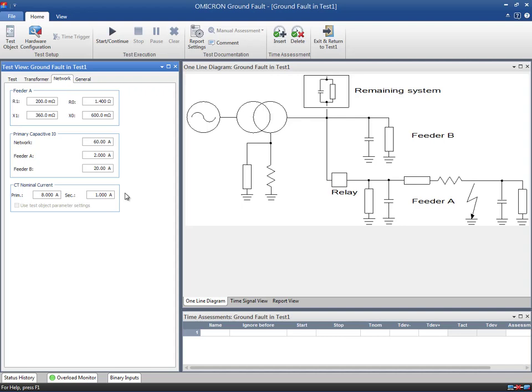If you get the message that the ground fault currents are too high, just increase the number of turns through the cable type CT. For secondary current injection, enter the CT ratio as specified in the datasheet. Select the checkbox to use the ratio from the test object.